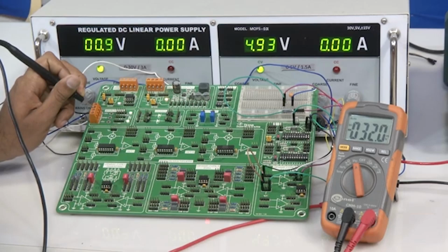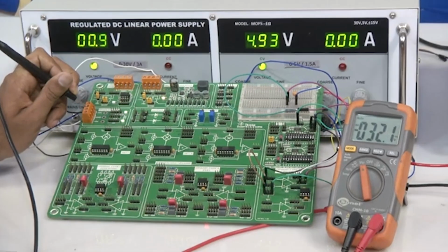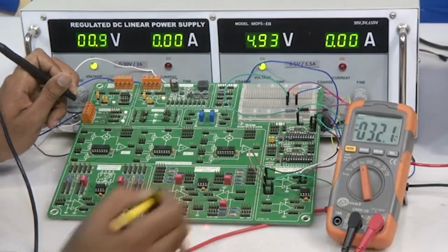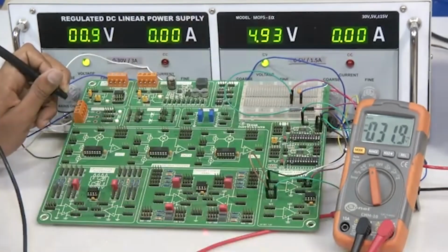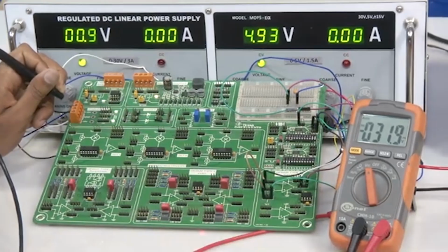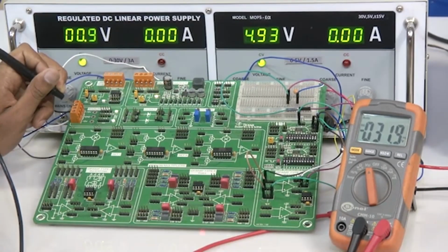So we got around 5.86, around 6 millivolt change. Now let's increase one more bit. Now we are keeping the other two bits high, so we are not changing one bit at a time, we are actually changing double, because we are not moving the other two bits to 0, we are keeping them as 1 and keep on increasing the bits to high, that is D0 and D1 are 1 now.